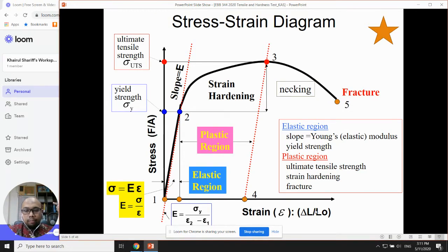Remember, implant in your mind, when we talk about the tensile test, the first graph that crosses your mind is the stress strain curve or the stress strain diagram. Here I give you a few tips in order to understand this graph. Number one, you need to understand how to draw, how to sketch the ideal shape of the stress strain curve. What is the meaning of the ideal shape? This curve, you need to see my mouse here.